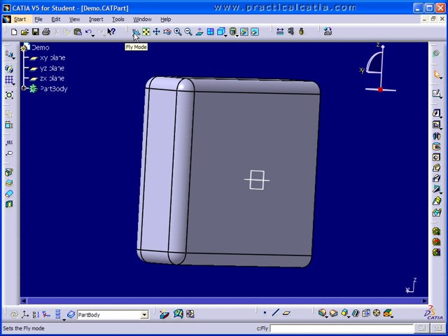a hole in our part so we have something to fly through. So let's make a modification to our solid. Now this solid was created from a sketch, and if we go in and modify the original sketch by putting a circle on the sketch, we will end up with a hole in the part. So let's take a look at how we do that.